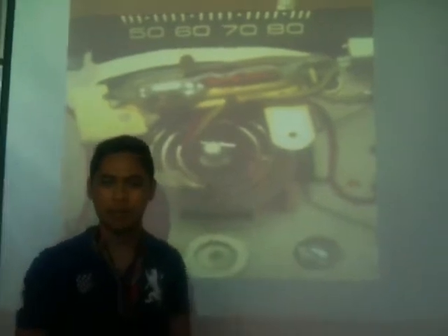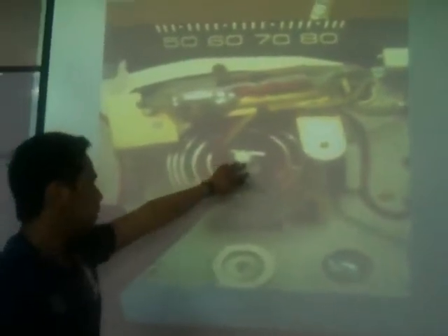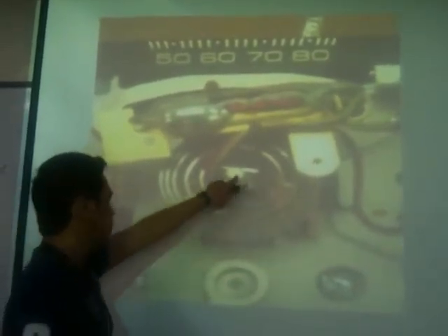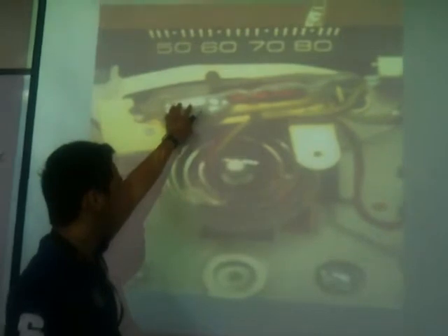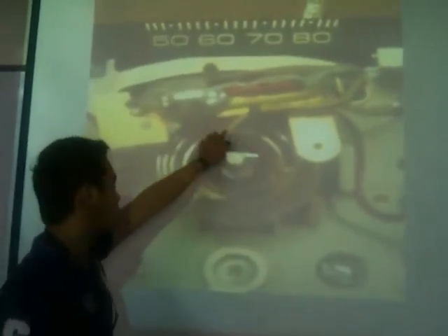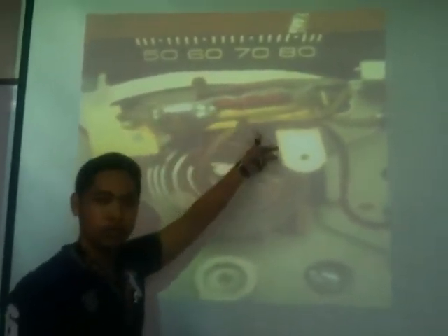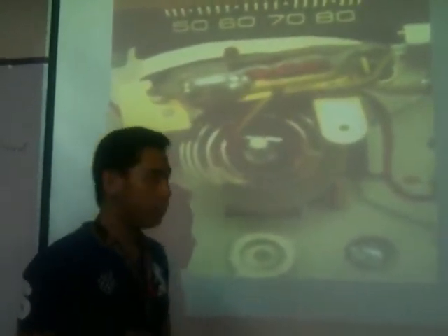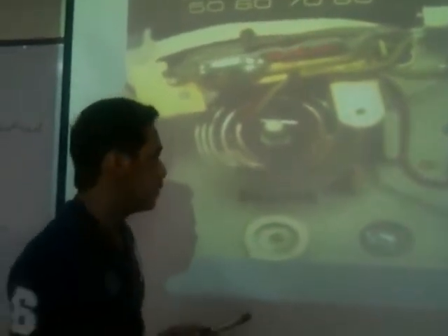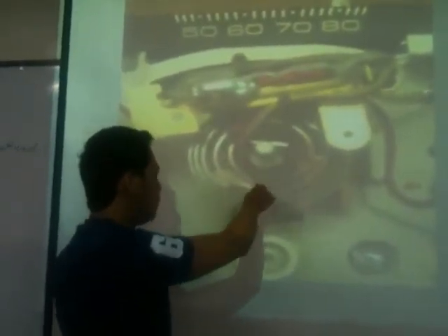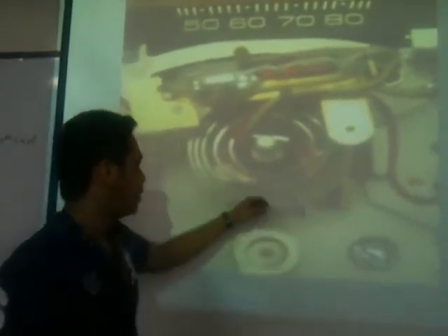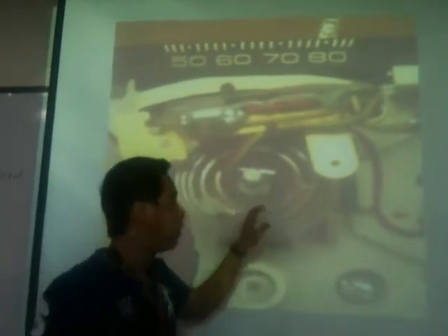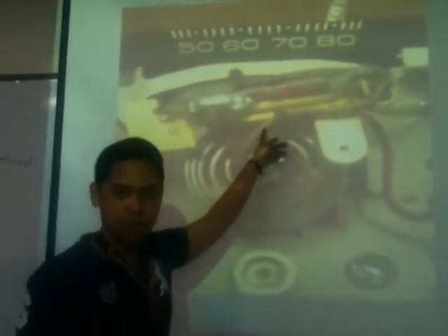A thermostat regulates the temperature of the room. Here, one end of the bimetallic strip, which is coiled, is at a fixed point. Another end of the coiled bimetallic strip is connected to the mercury switch. When the room reaches the desirable temperature or the set temperature, the bimetallic strip will also reach its desired length where it can switch the mercury switch on or off.